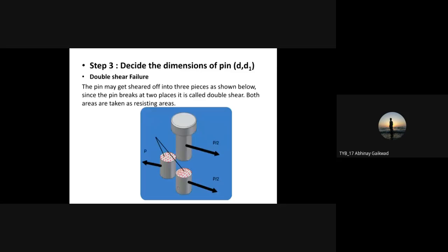Now this can be written in mathematical form. We can write P, the capital P which we have used for the load, is equal to 2. Why is this 2 used? That again we have to understand. In the case of the pin, shear does not occur at one place. Shear occurs at two places, which are separated out because of the double eye, which the single eye is trying to pull out, the same as in the quarter joint.